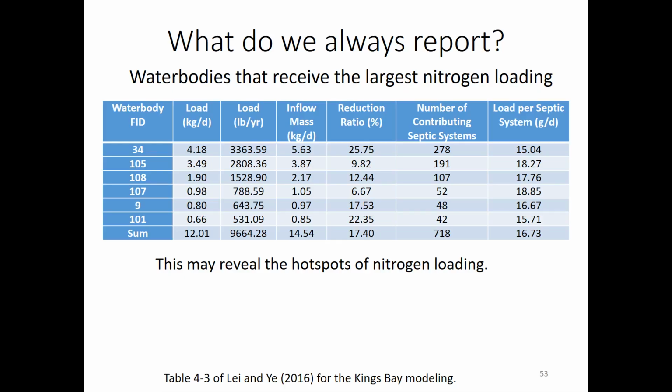That's pretty much it. So as a summary, this training video explains how we run ArcNLET for a situation without calibration. That means you have no data of hydraulic head and no data of nitrogen concentration. You just want to run the model and estimate the load, right? We suggest you run ArcNLET V1, not Vismod, because Vismod requires so many parameters that you may not have.